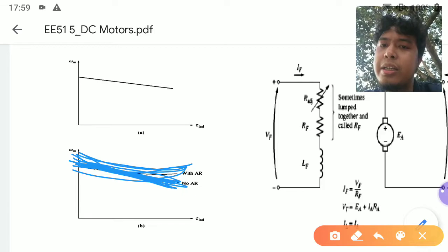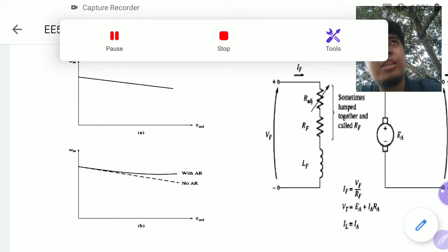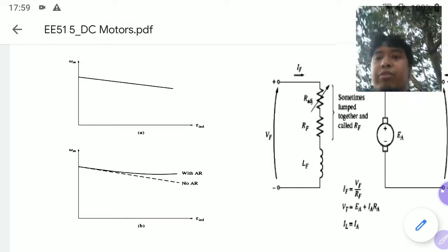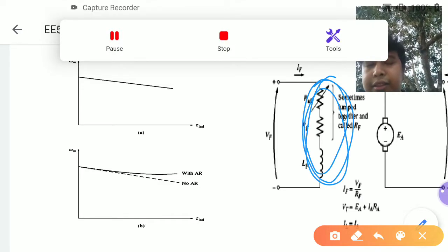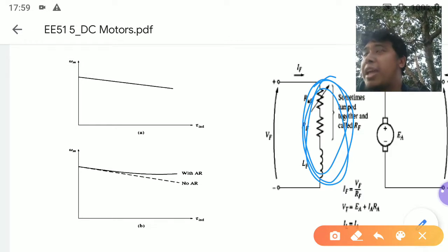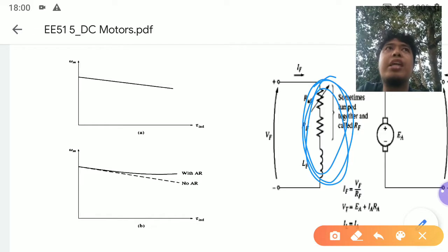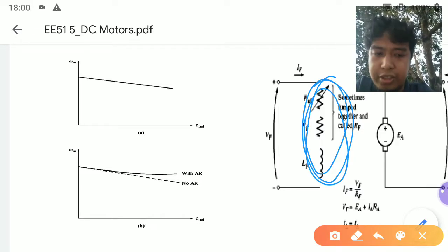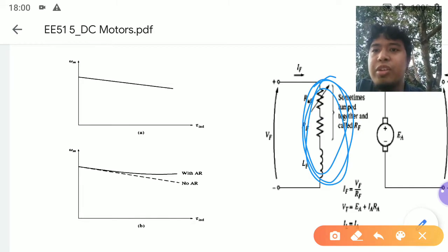As you increase the loading, you produce a magnetic field. Of course, you have the magnetic field here. Now, as you increase the loading, take note, your armature is made up of coils, and these coils receive more and more armature current, and because of that armature current, you produce another magnetic field on the coils, and that magnetic field actually aids in producing torque in the armature.